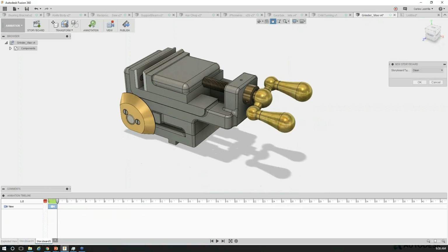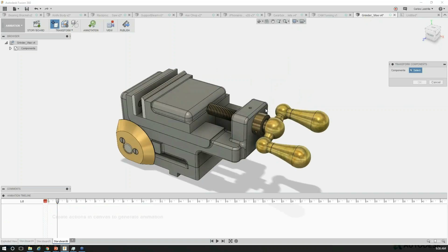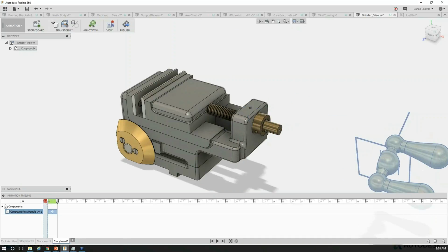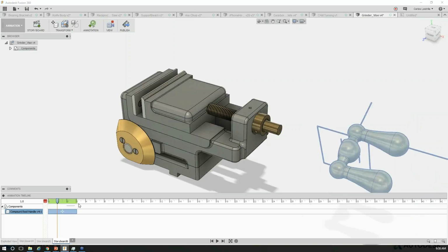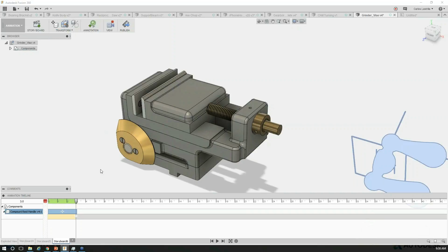So if you've used the Inventor presentation environment, it's very similar to that, where you've got a camera view, you set camera views, and then you apply transforms to components, where I'm going to drag this out there. And each of these transforms will actually be an entry into your timeline. So you can say that's going to take 3 seconds to move from here to there. All right? And you can also say that once it gets there, I want to turn off or fade it out. So I'm going to fade this one out a bit.